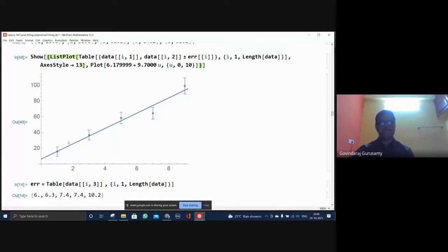So when you use frame, corresponding frame related options should be explored. Okay. When I have axis, I have only x-axis and y-axis. There is no frame. So the corresponding options should be taken care of, and then see that it is consistently varying properly. Otherwise, it will be a mess. Axis style and frame style will be different. Frame label is different. Okay. Here it is a plot label. There is a frame label.